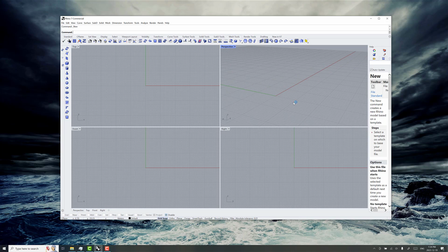Now, the first thing to note is that the Rhino3D toolset is expecting a file input in a certain format with a certain reference frame configuration, and we strongly recommend you set everything up with the origin of the frame at the aft perpendicular of the vessel. That'll make it really easy to key in particulars for the ship in the future based on station number, which will be keyed from either the forward or aft perpendicular accordingly. The other thing that the Rhino3D toolset's looking for is a positive Z up and the location at the baseline of the vessel. So for our box barge, what that means is we are going to be